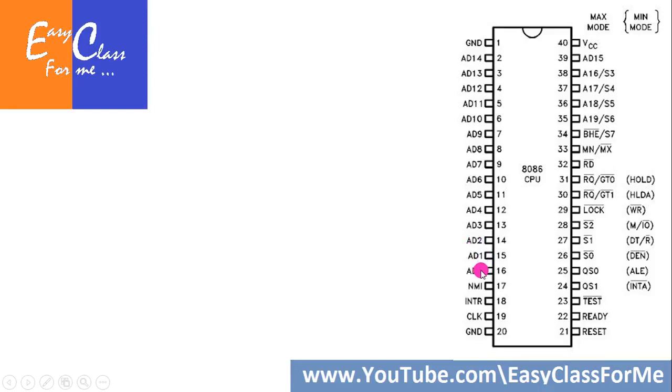Since from 0 to 15 there are a total of 16 pins, the data bus can be completely accommodated in that. But since the address is of 20 bits, we have A16, A17, A18 and A19. These 4 pins are multiplexed with some status signals, which we will come to very soon.